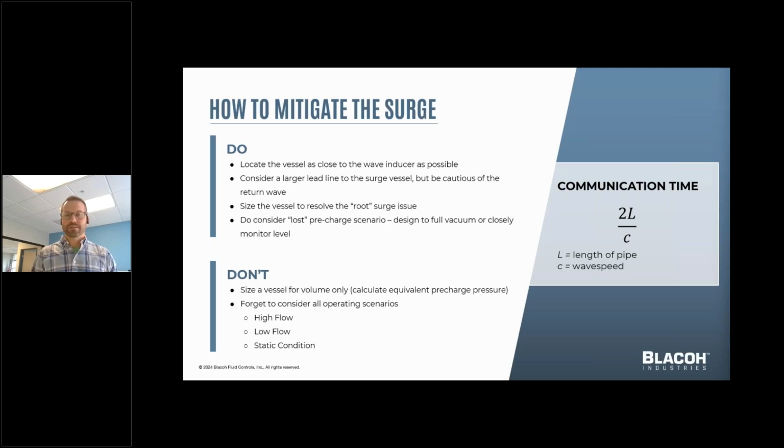If you're seeing damage or you're seeing short pump life or you're seeing replacements of components that continue to break, spending the time to do the transient analysis and locating and selecting the right kind of vessel can go a long way to saving you a lot of maintenance costs and a lot of headaches. What we also need to make sure we don't do is only size for one condition.